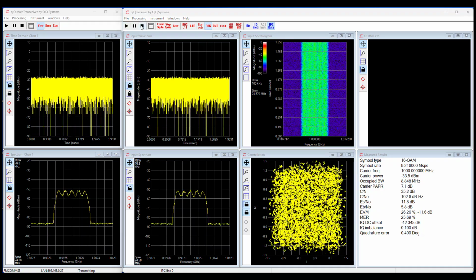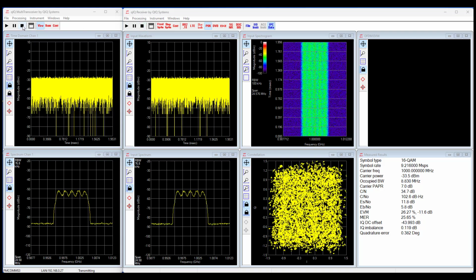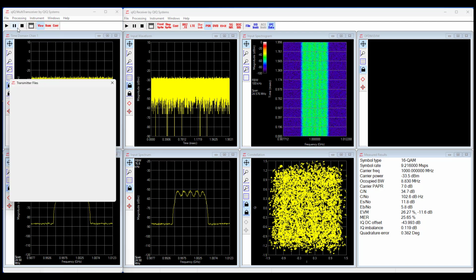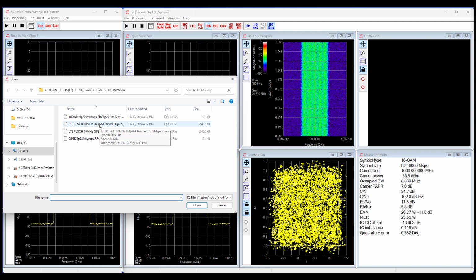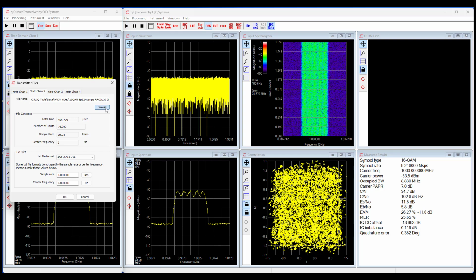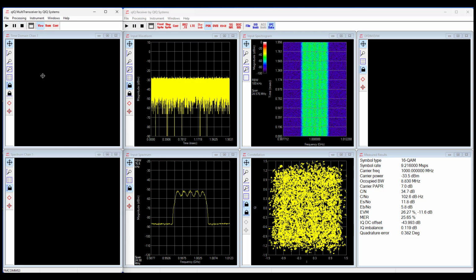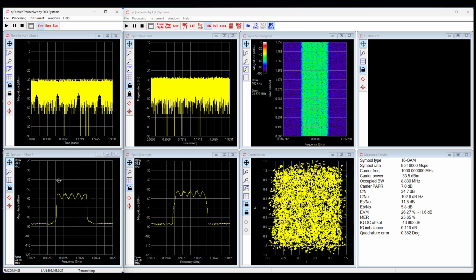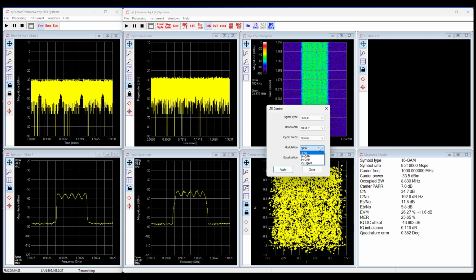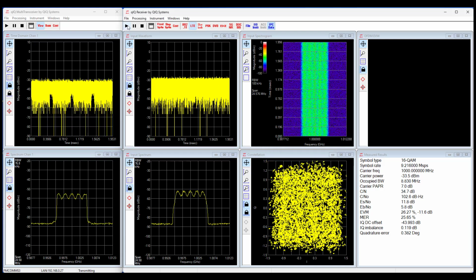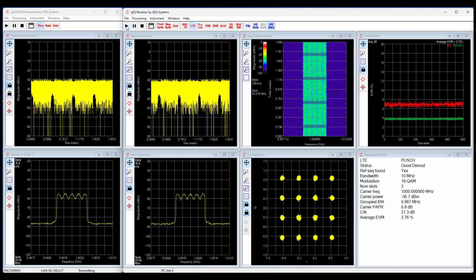And for our big finish, let's switch over to an OFDM type of waveform. So I'm going to stop both of these. I'm going to go over here and say for transmitter 1, let's send it our 16 QAM version of LTE. Push. Do that in both of these. I'm not going to make any change at all to the multipath. So same looking pattern on the top of the OFDM signal that we saw for the 16 QAM signal. I'm going to go over here and say we're going to do an LTE DMOD with 16 QAM symbols on the top of those, and start that running, and wow, that's a pretty good DMOD.